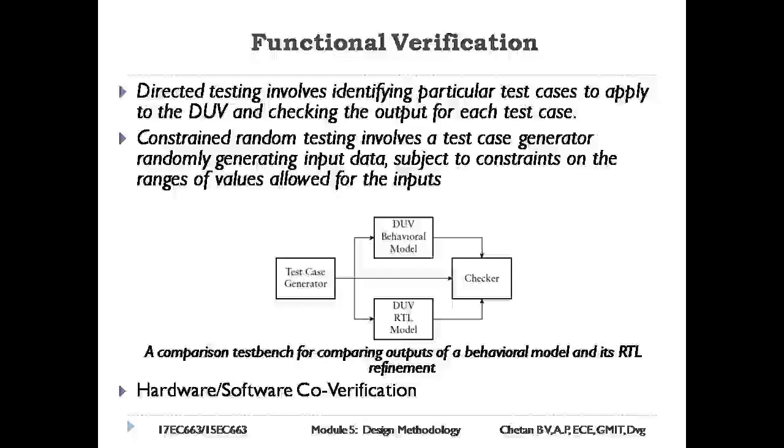Formal verification allows complete verification that a component meets a specification. The specification is embodied in one or more asserted properties expressed in a property specification language such as PSL. A property can be as simple as a Boolean expression relating the values of signals in the design. A formal verification tool performs state space exploration to verify the asserted properties. Writing properties that completely and accurately capture the intent of a specification is very difficult.